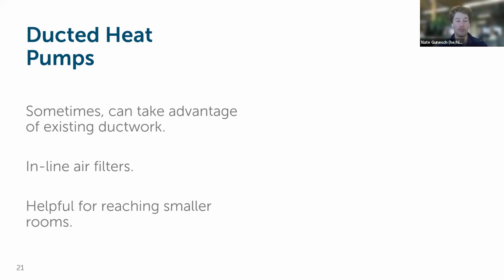I will say a lot of people who move to heat pumps start to say, oh, wow, it's really nice that my house doesn't fluctuate every 5 minutes or every 15 minutes. They say it's nice that it stays a consistent temperature all the time. However, that consistent output of temperature is usually a lower temperature. So it's worth having a conversation with the contractor. Can I take advantage of my existing ductwork? Often the answer is no, but if you can, a ducted heat pump is a really good solution.